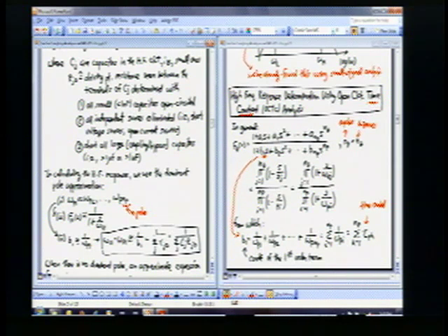I'll say this many times during this semester, but there are a lot of circuit designers out there, and the worst circuit designer is the one who will build a circuit, plug it into SPICE immediately, and never write anything down. Circuit design is more intuition. It's your understanding that if I change this capacitor value, or if I move this transistor to this configuration, it's going to affect the frequency response this way.